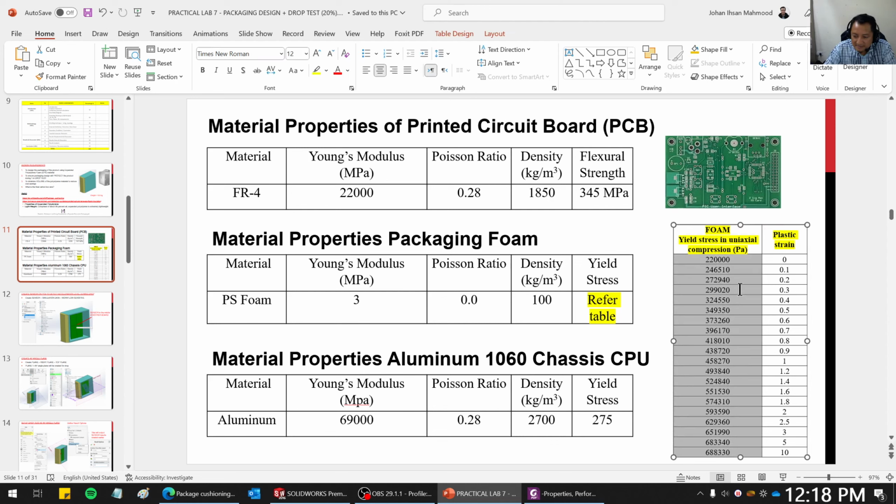Okay, so let's take a look at your design. In your design, you can put in one sensor. Under sensor, you can key in simulation data, workflow sensitive, and click the vertex on the motherboard. This will output the result when it is undergoing drop test. We are going to drop test at a 45-degree angle. There's no need to drop test at a flat 0-degree angle.